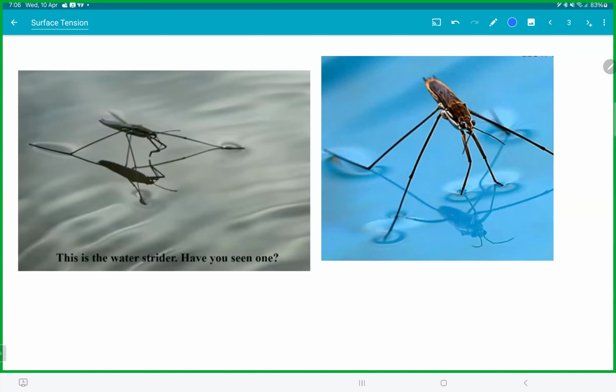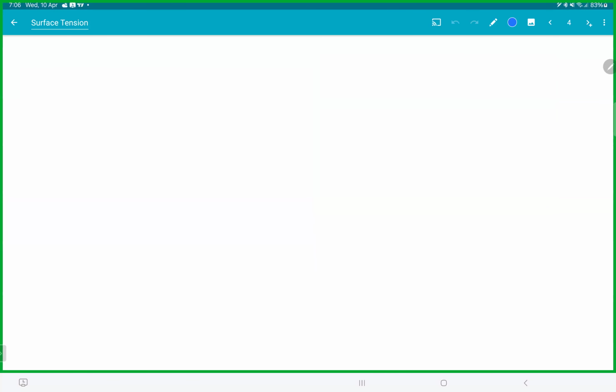Chalo, let's start everyone. So we kept on talking surface tension, surface acts like a membrane and stuff, but what is the surface exactly? So surface is nothing but a thickness of 15 molecular diameters. So basically that's your sphere of influence, at the interface of the mediums.